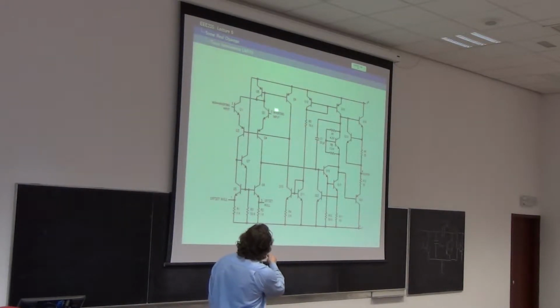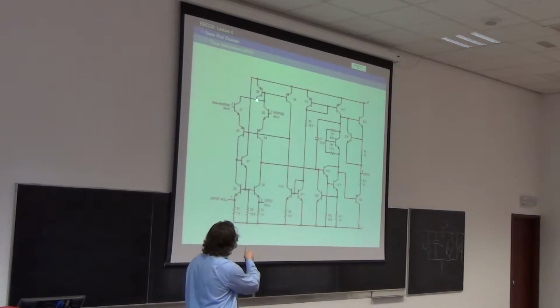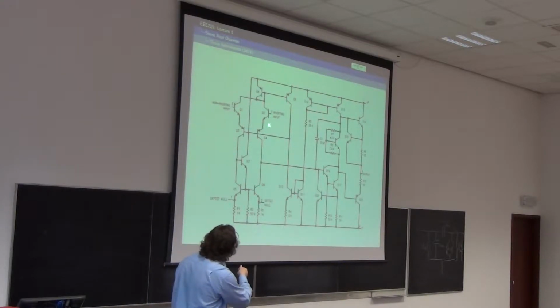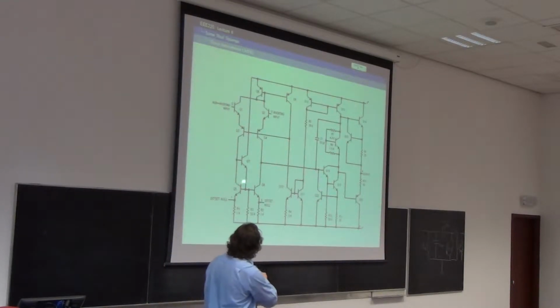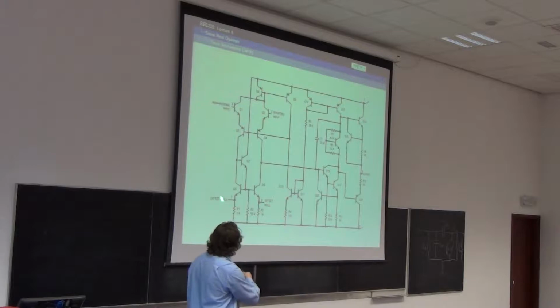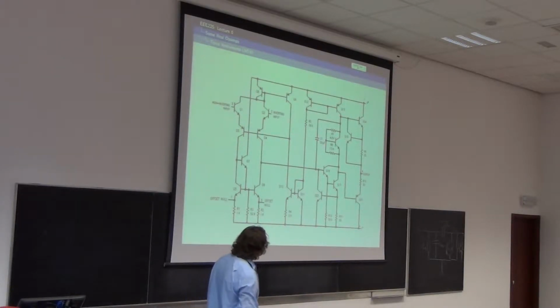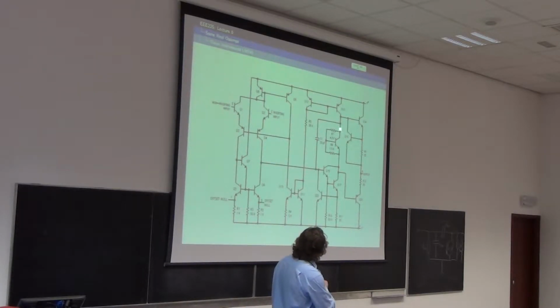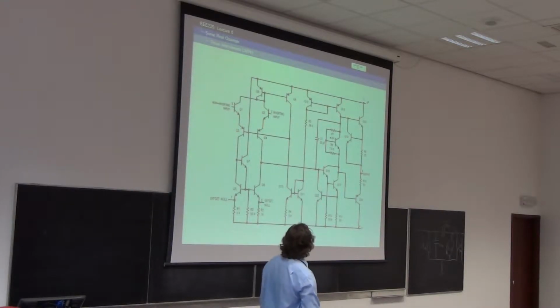This business here is a current mirror, and that provides our current source for our sort of quasi-differential amplifier, which is this lot. This business is just a current mirror, also degenerated by those two. We've still got a Darlington, and this is straight out of my circuit. Well, it says my circuit. I don't own it by any means.